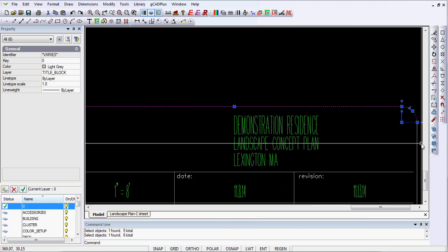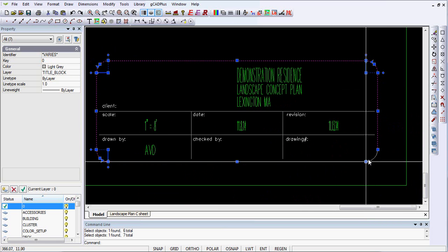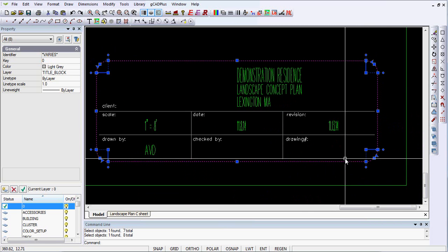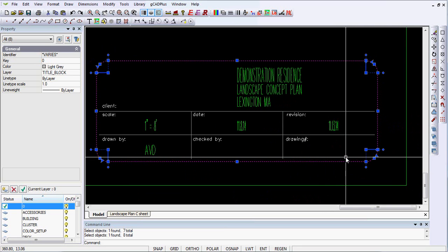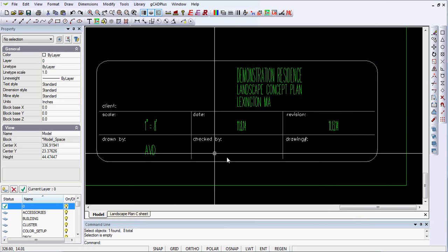So what I'm now doing is selecting each part of what was a polyline, and now I'm going to join them. There is actually an easier way. Just do a rectangle and put a radius of curvature onto that polyline. Let's do that. That would be a far neater and more elegant way to do it.